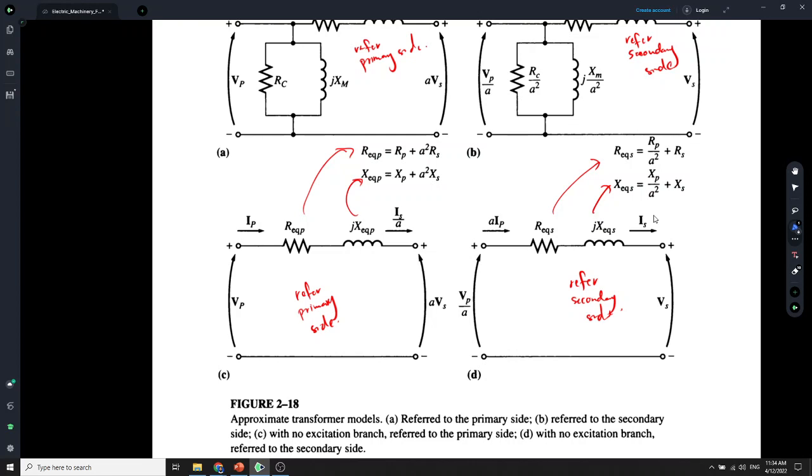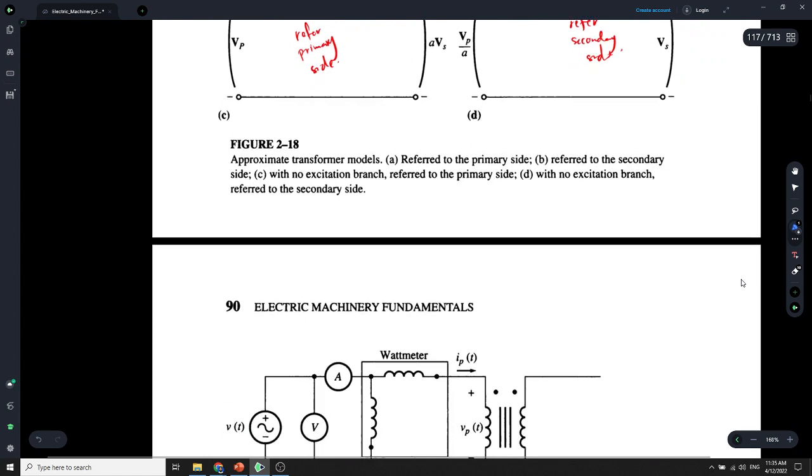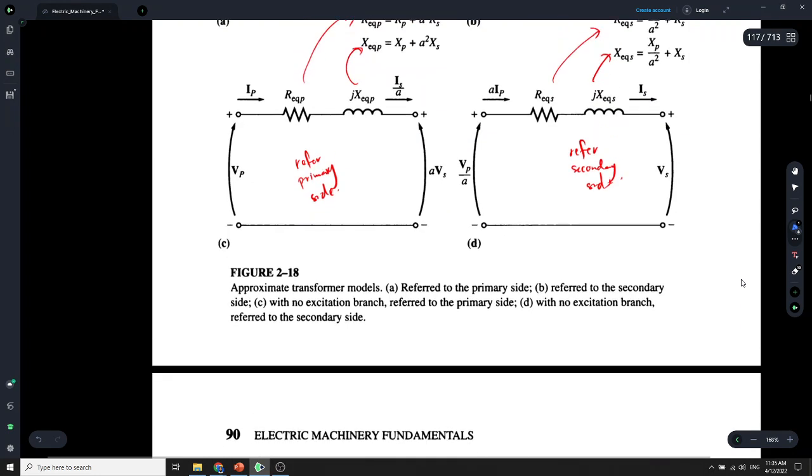Then we design the equivalent circuit, and from it we know that the current to the junction is small, so we can remove or ignore it, and the circuit becomes a series circuit. We also know how to transfer from the primary side to the secondary side, and secondary to primary. Do you understand until now? Understood, Doctor. Okay, nice.